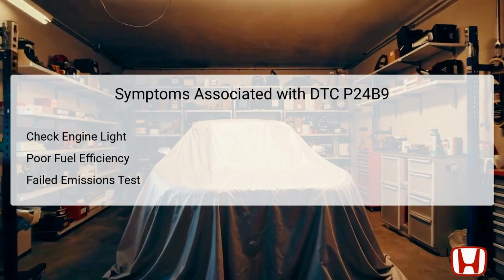Common symptoms associated with DTC P24B9 include the illumination of the check engine light, CEL, reduced fuel efficiency, and potential failure during emissions testing. The CEL warns drivers of underlying issues within the vehicle's emission control system, prompting immediate attention to the issue. Poor fuel efficiency can result from an improperly functioning EVAP system that allows gasoline vapors to escape, leading to incorrect engine management by the PCM.